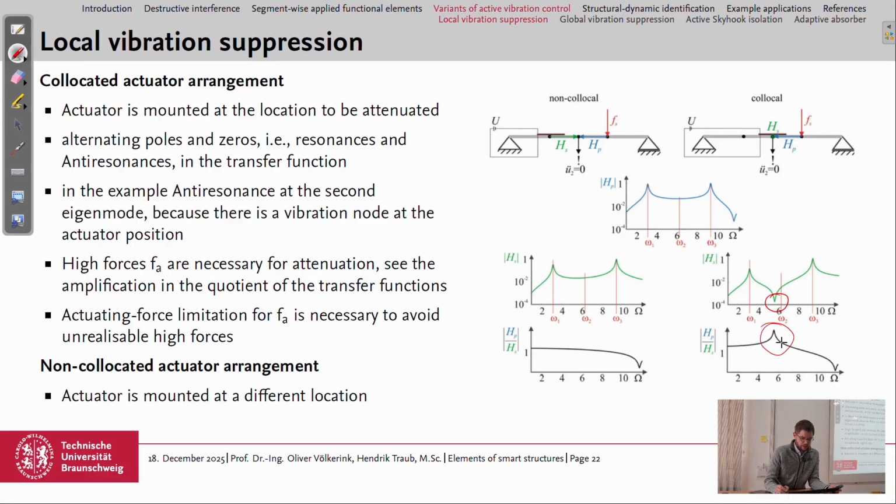This means that we need really high forces in this arrangement to calm down the structure at this point for this frequency near the second eigenfrequency. So we can directly read from this fraction of the transfer functions for which frequency we need high forces to calm down the vibration.